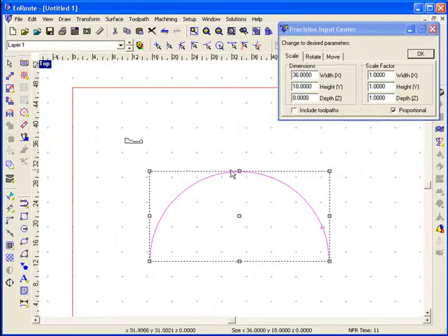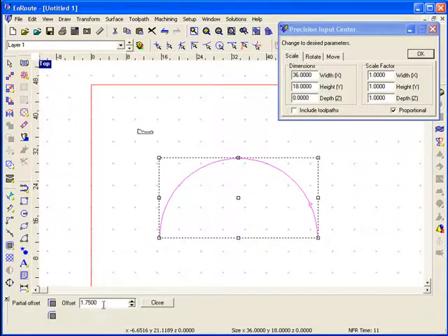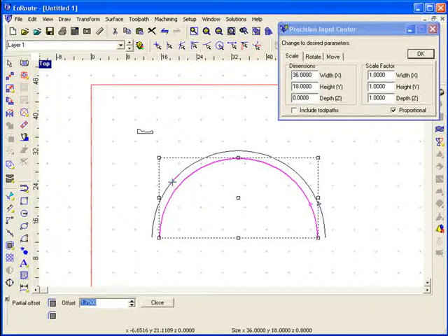So I'm going to make an outer shape here that's also 3.5 inches so that I can extrude this profile along that shape. I'll do that by going to the partial offset tool and creating an offset of 1.75 inches, which is half of the total 3.5 inches. I'll select this line and click to the outside, then select the new line and click once again to the outside.